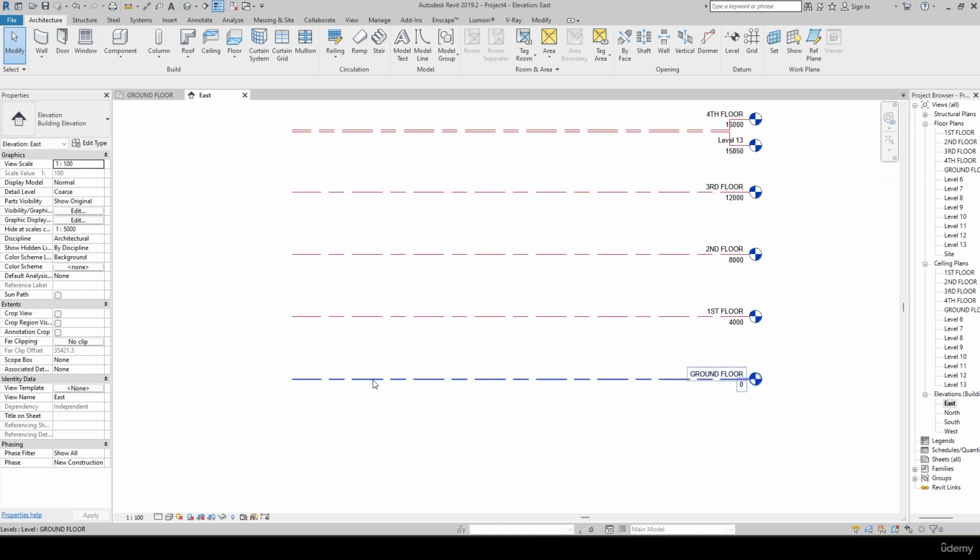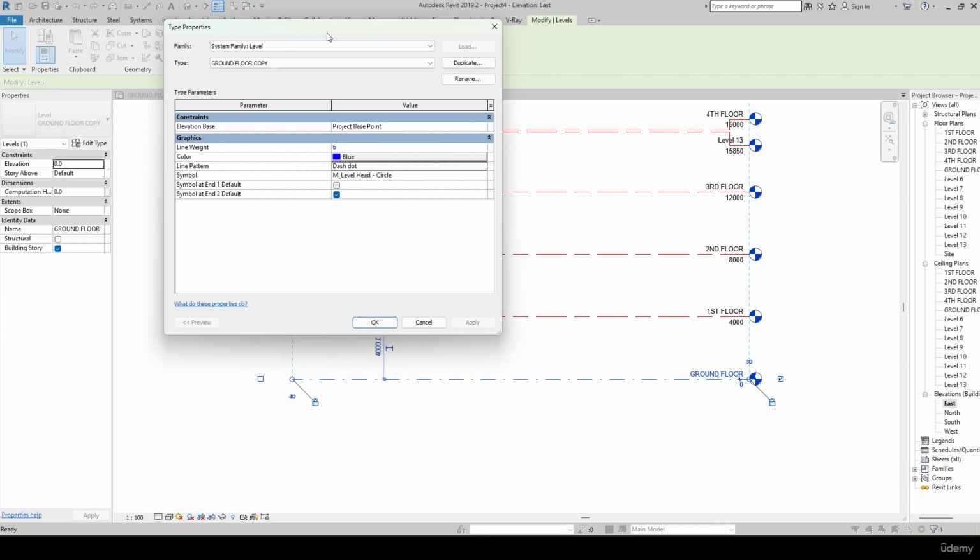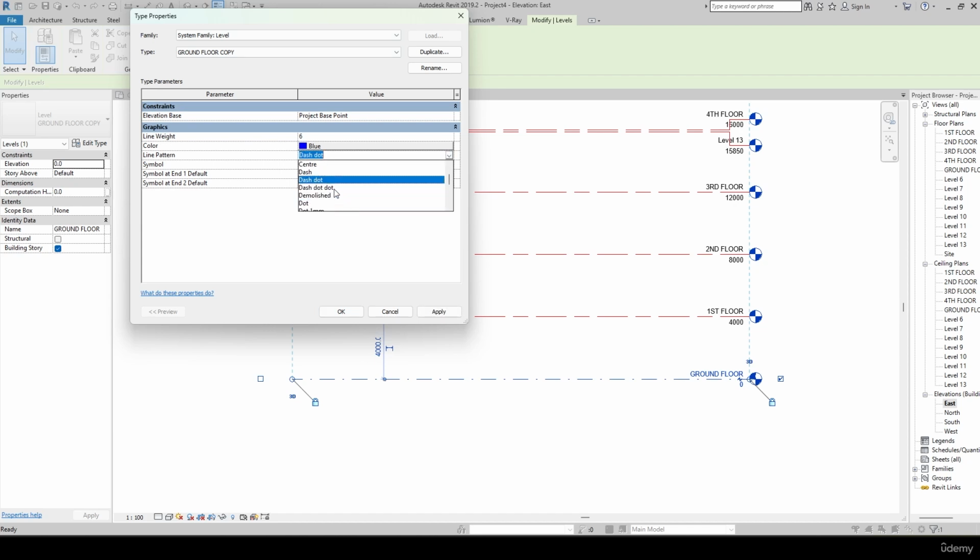So again, if you want to change the styling part, if I go here I can change the line pattern. As of now the center, if you want you can give the dash, apply here, and you can find the dash. If you want, solid is also possible. Basically I just keep this as dash and dot, right? So many other types of notation are available. You can select whichever pattern you want. As of now, I'll simply select the center and apply.